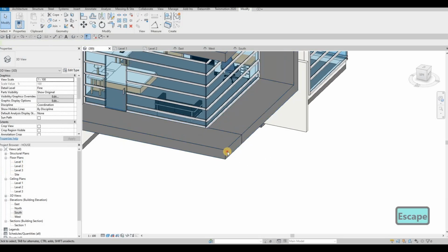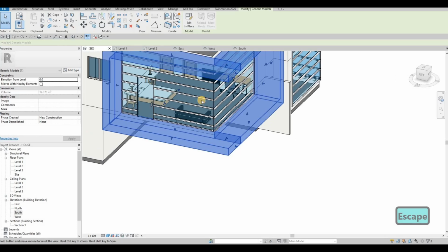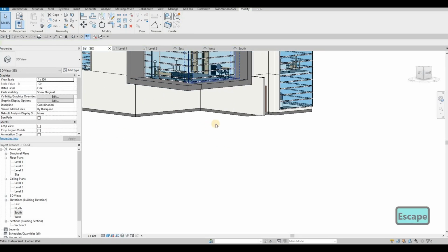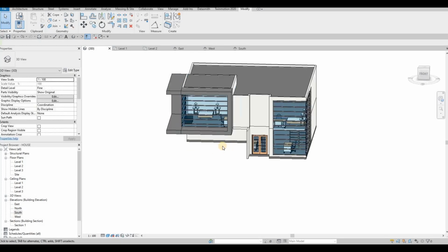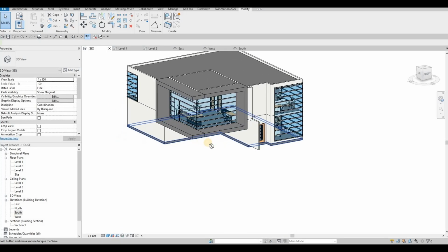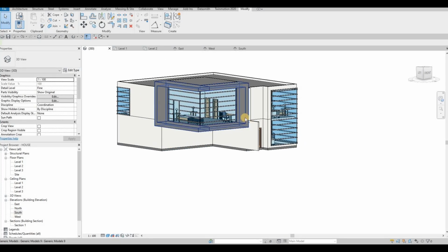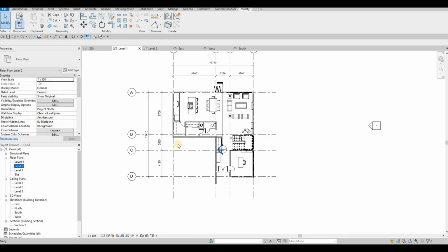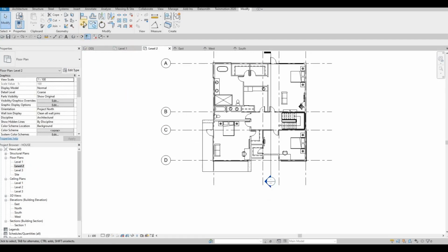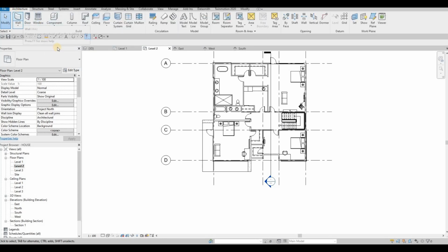What I'm probably gonna do is, because this is the front, yeah, the seam is not gonna be shown, it's gonna blend in. We just need a curtain wall right here, so go to level 2, and then we could just add curtain wall.